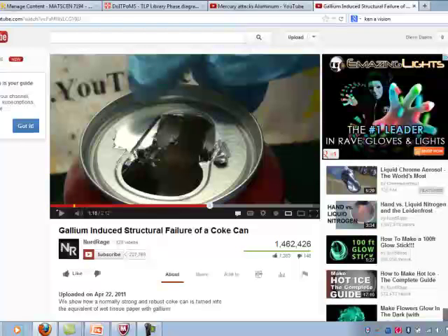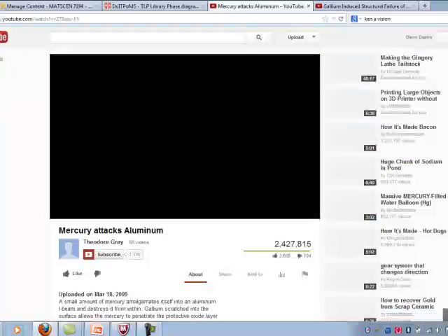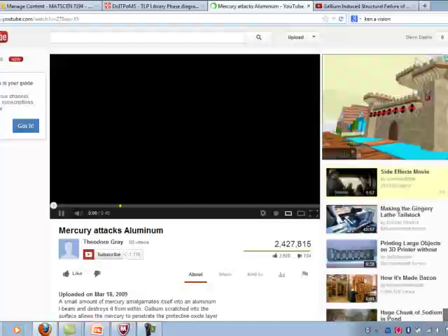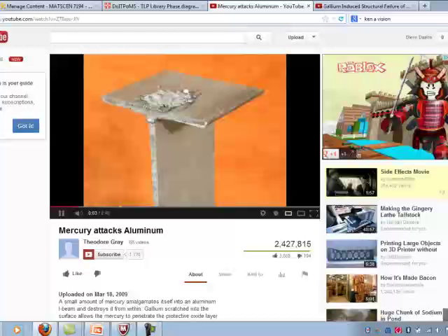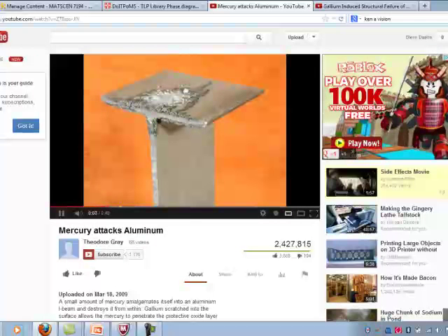These phase diagrams matter. Again, to me, the incredible thing about all of this in the science is if you understand what's going on, you can be very predictive about that. And I'll show you that mercury has a very similar phase diagram. Therefore, you expect it'll do something very, very similar. And here's mercury on an aluminum beam. And this is linked to the next slide. There's mercury put on the beam, and you can see that it's diffusing in and causing havoc to the internal structure.